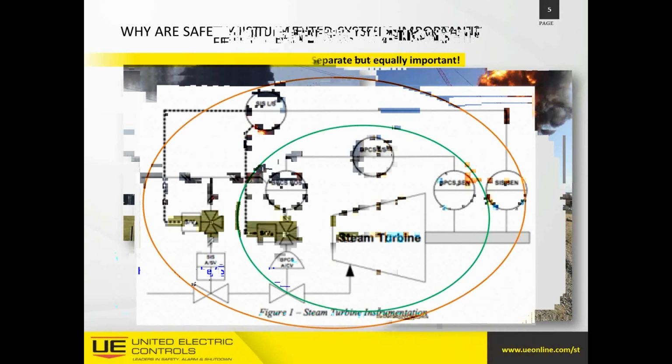Now, I talked about this international standard called 61511. That 61511 applies very specifically to the chemical, petrochemical, power, oil and gas industry. That is the standard that contains all of the practices and the measurements to determine how to build a safety instrumented system. But what rides closely to 61511 is another standard called 61508. These are two very important standards to understand.